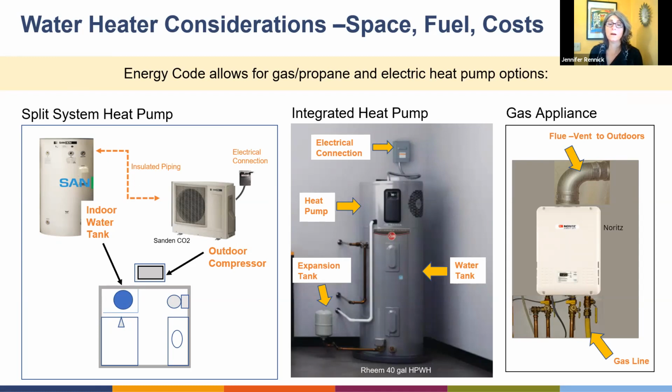If they have an existing water heater and they want to replace it with a heat pump water heater, really you want to do it before the unit fails, because in a lot of cases you have to have an electrician come out to run the electric connection necessary, and it would be on a dedicated circuit breaker. Rheem is coming out with a unit that's only 15 amps. So that kind of goes back to that question too about how many amps do I need? How much of a sub panel do I need? So with the 15 amp heat pump water heater, that would be ideal to keep your amperage on your panels down.